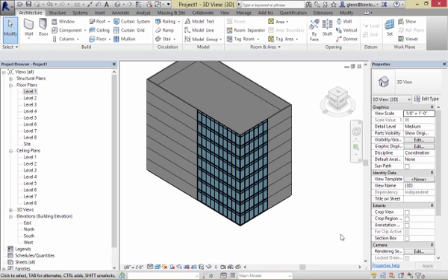We could have done that. I'm going to show you another way to create that hole, and it's even a little more powerful. Very good, you were right. If we would have cut the hole in the floor and then copied that same hole, it would go up. The difference, I'm just going to give you an idea of what the difference is. If I copy these elements, the truth is these are all independent still. So if I decide later to change the size of the hole on one floor, it wouldn't automatically change the hole on all the floors, because they're copied instances that are considered separate.